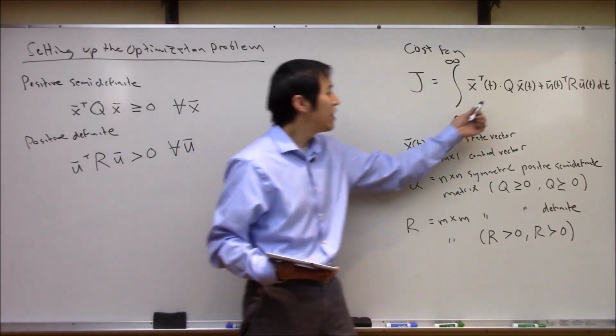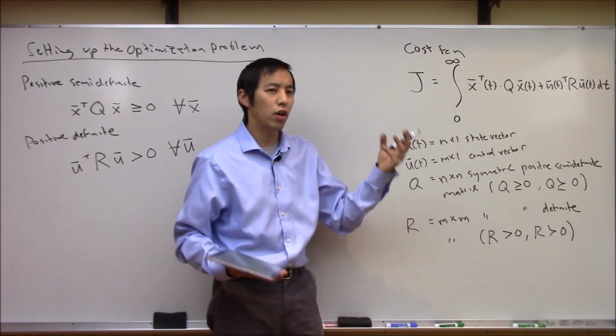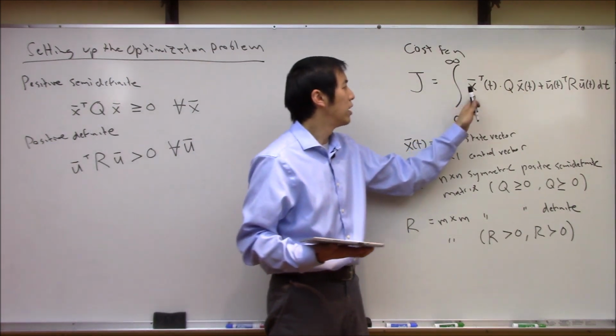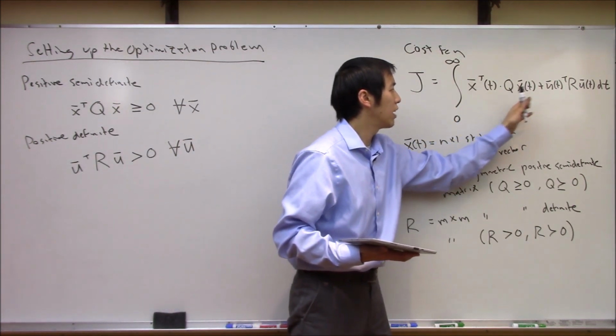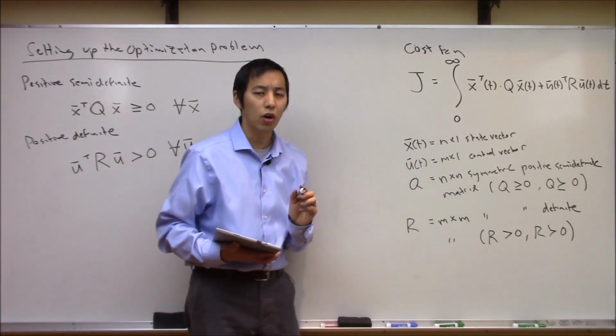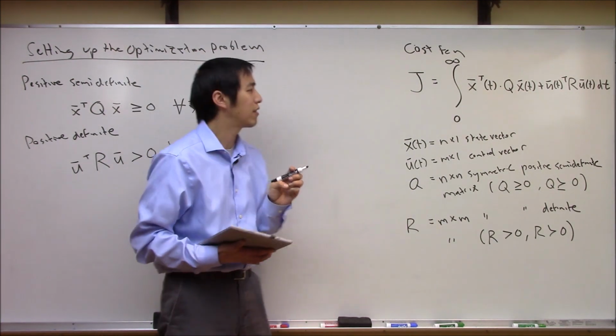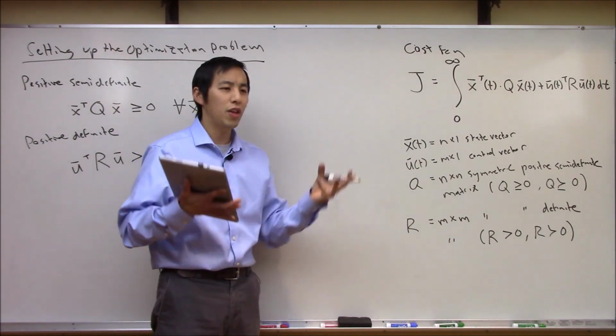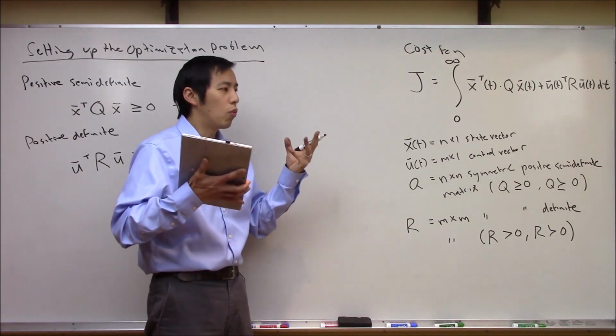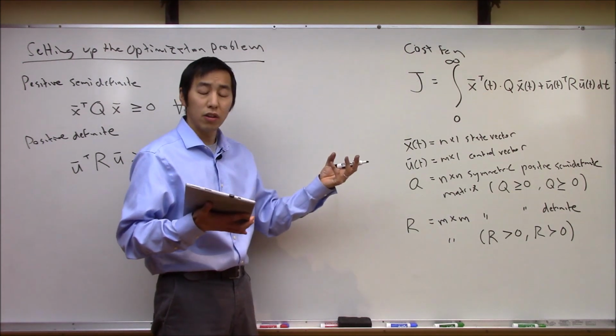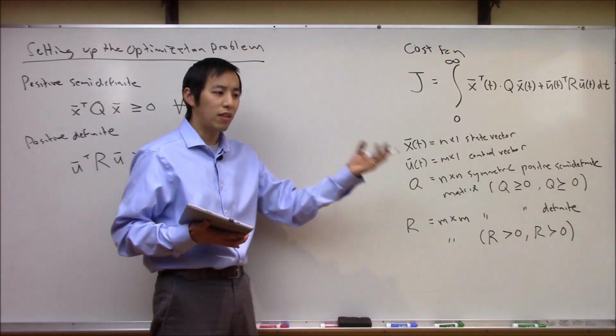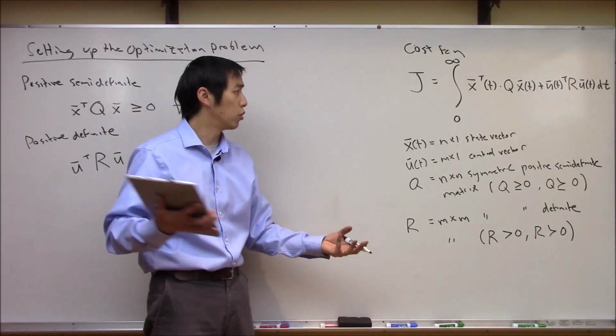In this case, Q and R trade off non-zero states versus non-zero controls. We're going to take a closer look at that in a second, but I wanted to plant that seed in your head right now. Let's start thinking about Q and R as weights to determine how much we value states versus how much we value controls.